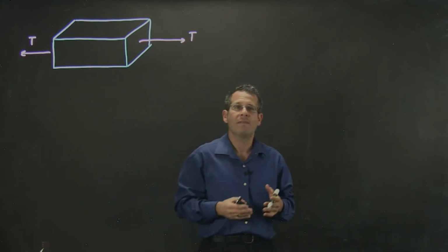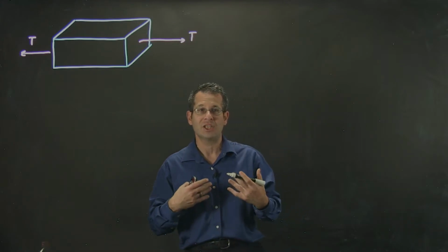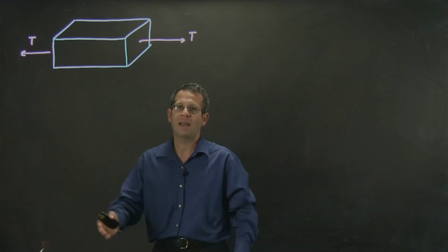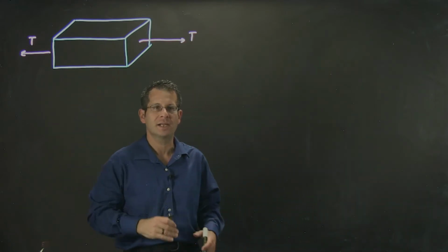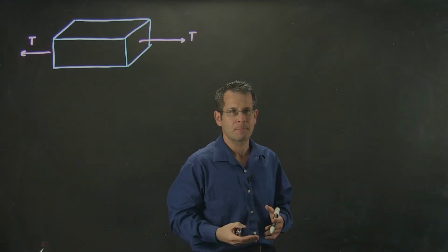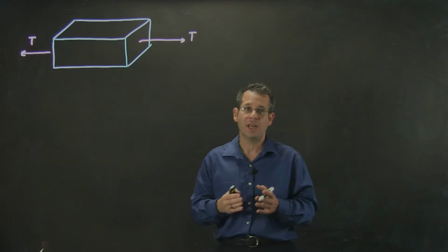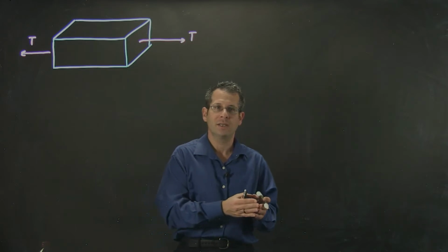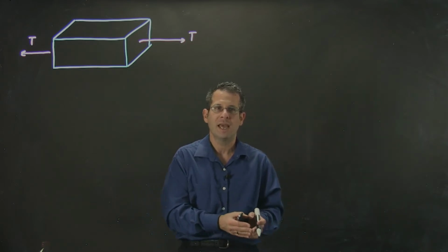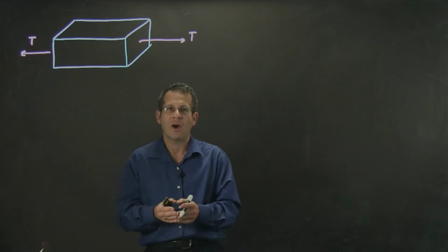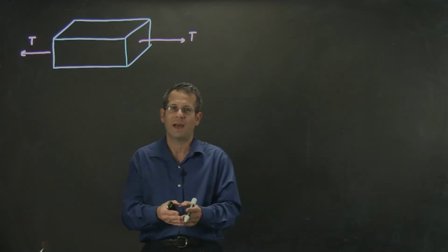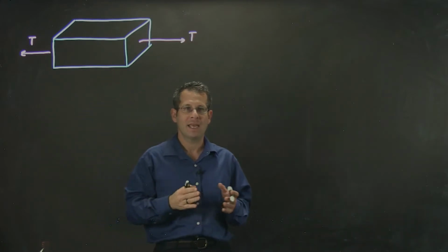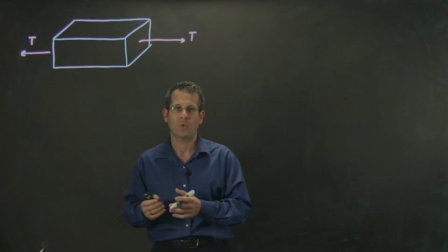One of the principal reasons we as mechanical engineers do finite element analysis is to determine if the actual stresses inside of our object are anywhere near our yield stress. But remember, in the last video, I reminded you that our stress is not a single number that we can compare to our yield stress, which is a property of the material. It has 6 different components. I only find a single scalar value for stress once I determine a plane at which I am calculating the stress normal to that plane.